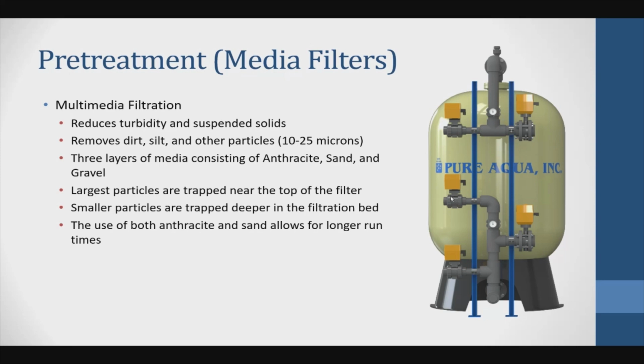So that valve is going to be open, that valve is going to be closed, that valve is going to be closed, that valve is going to be closed, and that valve is going to be open. The water is going to go from here, from the bottom. It's going to lift up the media, take all the dirt and the suspended solids that are accumulated inside the filter and push it out to that valve, and that valve is going to send the water to the drain.